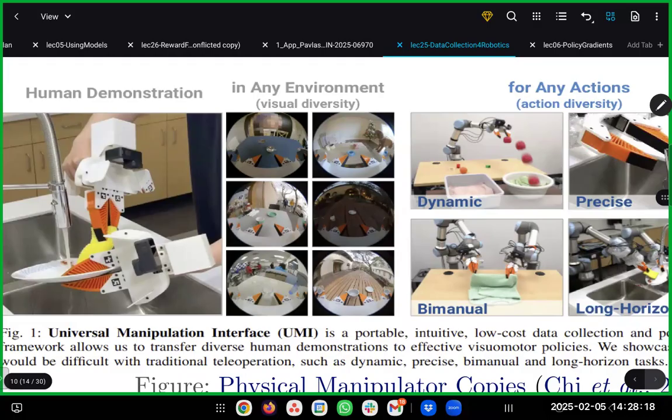Well, at the moment, this would be just data, and then depending on how the data is massaged a little bit, it can be used for different types of learning. So this is probably going to be used for behavior cloning. And maybe one example of this, which is done right now, and you'll get to see some of this for homework too, is essentially the output for the behavior clone policy is this, where it's just going to be the rotation and location of the hand and whether or not the gripper is closed or open.